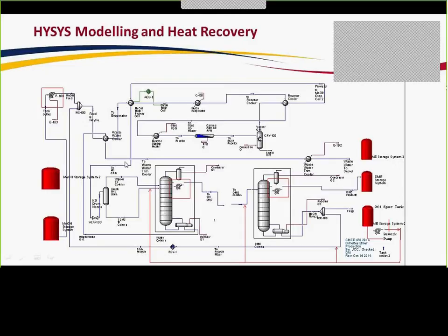After the second heat exchanger, it partially condenses, so we send it into a knockout drum, and that separates the vapor from the liquid stream. After the knockout drum, it gets fed into the first distillation column in two separate streams to increase the column efficiency. This column was optimized around the bottom of the column where the water product's coming off so we could meet our environmental regulations.